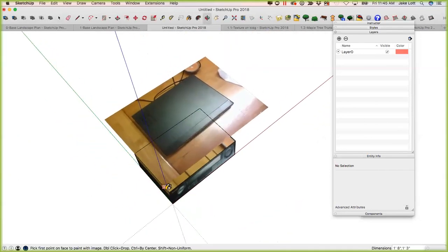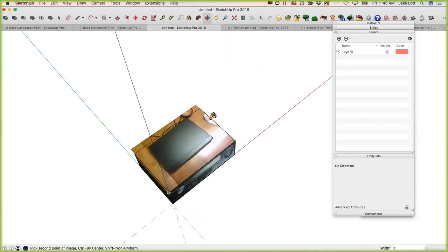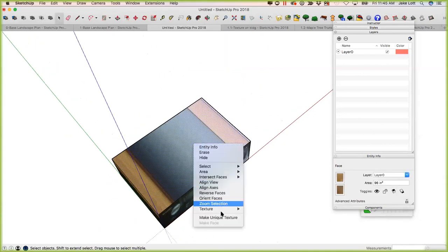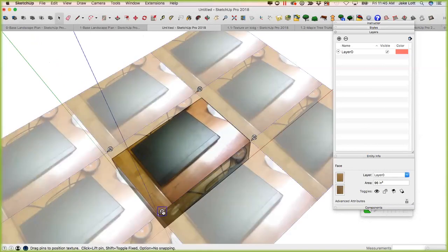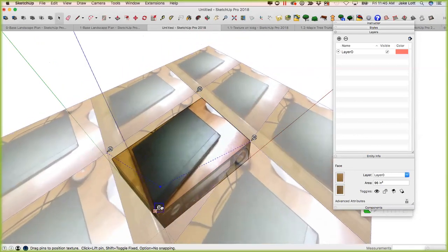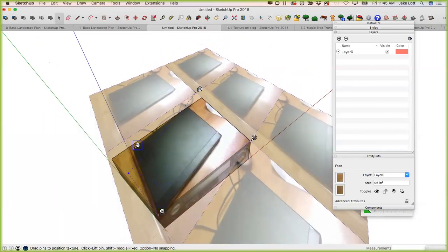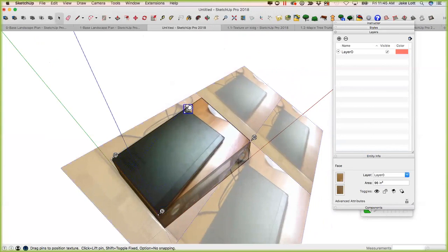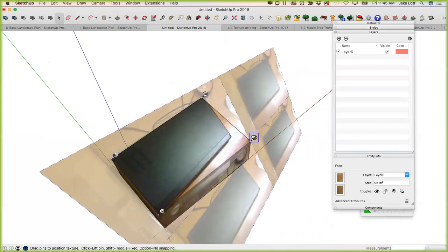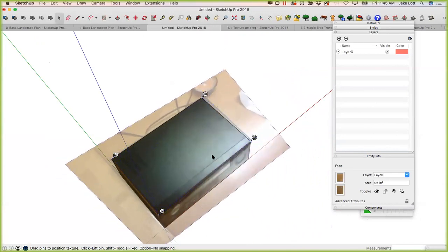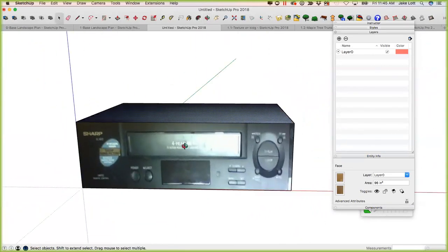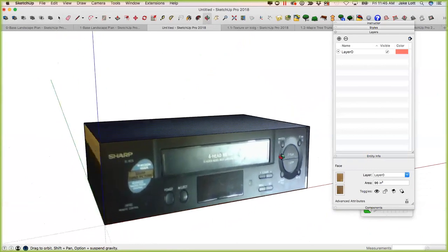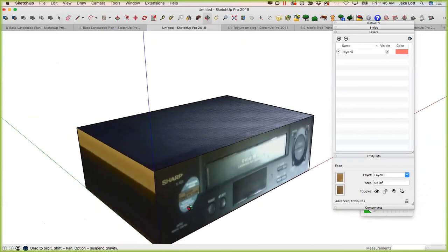So now obviously it's got all kinds of weird things going on on the image side of things, but we can go ahead and do that same type of thing. We can import, not use as an image, but use as a texture. And I've got all these other ones. So here's a top version. If we import it, we can just drag it out and place it on there for now. Again, right click. We'll not project it. And position it. Grab the corners. Just like that.